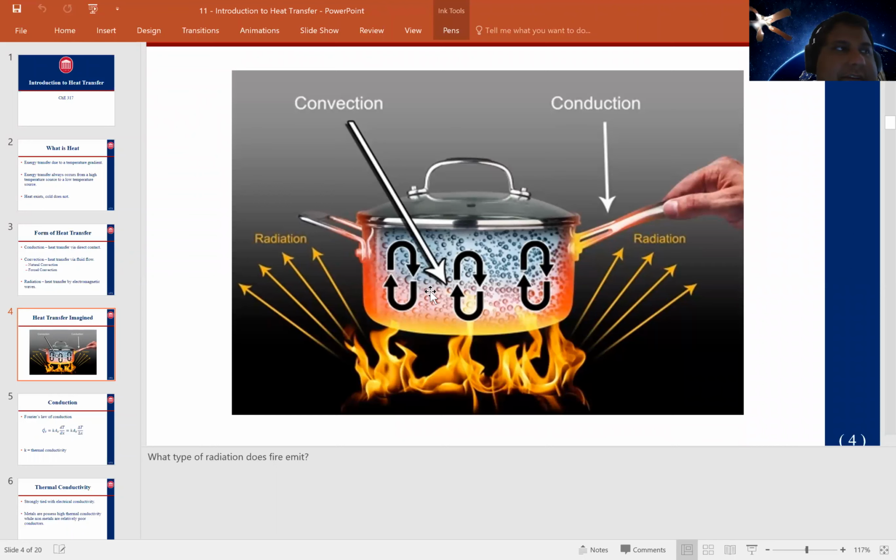That differs from forced convection, where the fluid is forced via a pump or compressor, where you're inputting energy into the system to cause the fluid flow to occur, which differs from natural convection, where the fluid flow occurs due to the presence and emergence of temperature gradients.